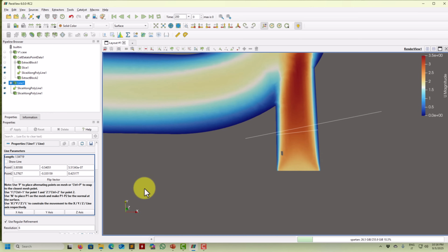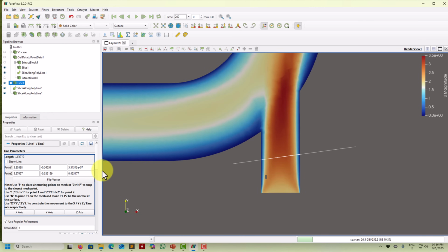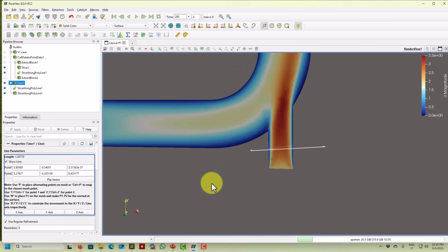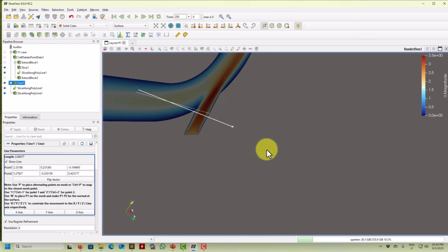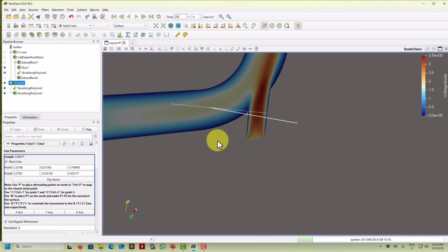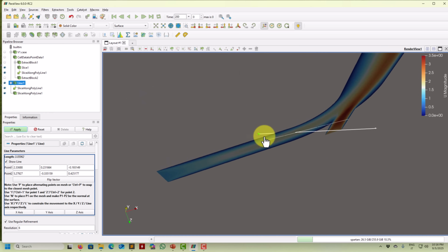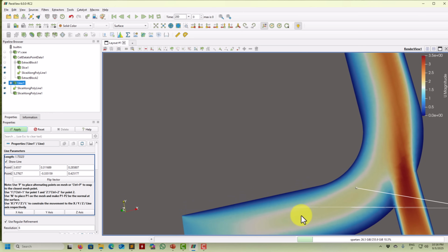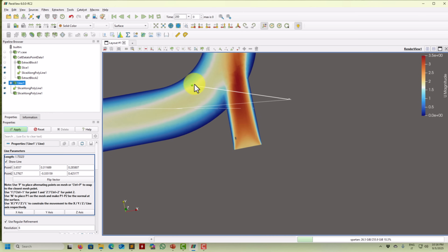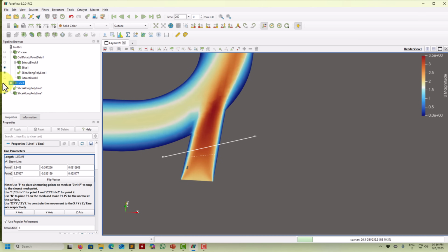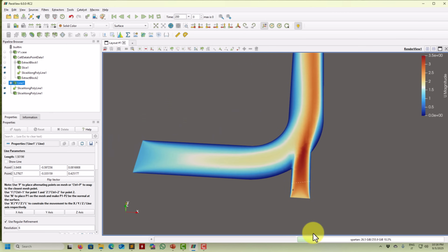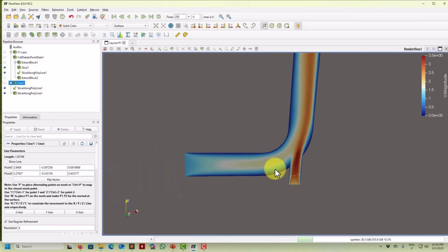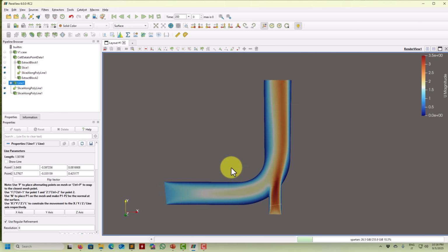This is very cool. I do it a lot for some reason, sometimes I need to do it. And look at what happened, this is interactive. If I move like this, it will project everything there. Now you have that line, and in theory you can release streamlines from that line. But let me constrain it, and put it here so I know it's releasing just from there. Hopefully you get the idea. This polyline you can now make complex, so it's very nice and very useful, depending on what you're trying to do.